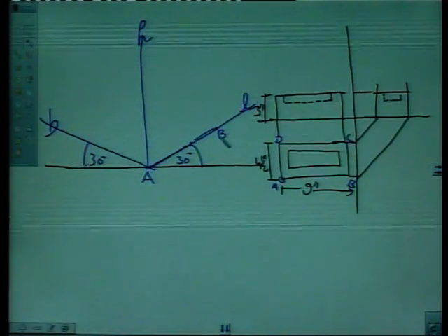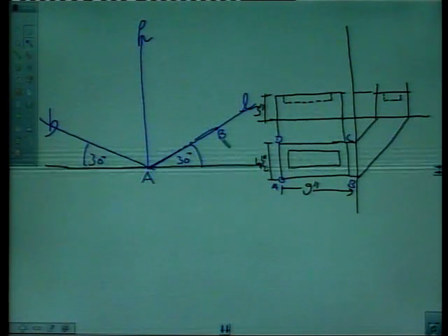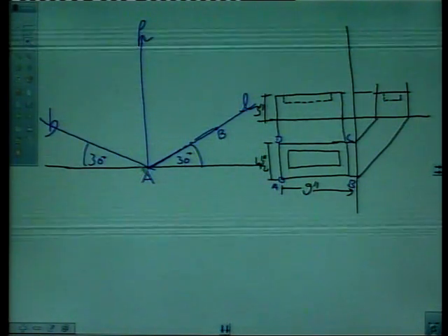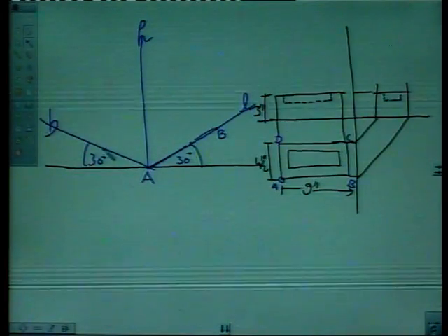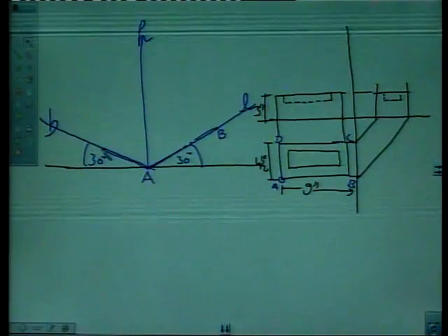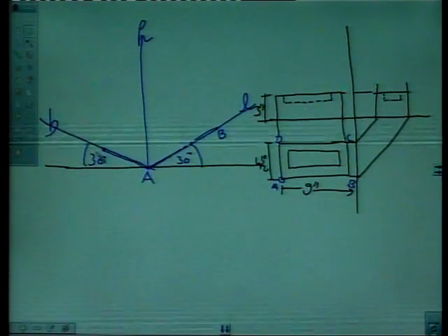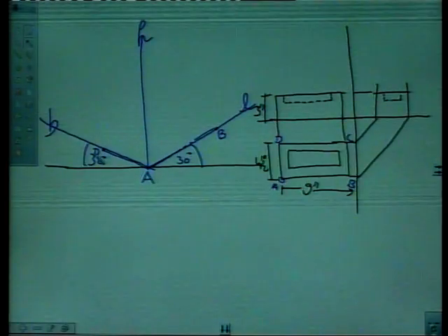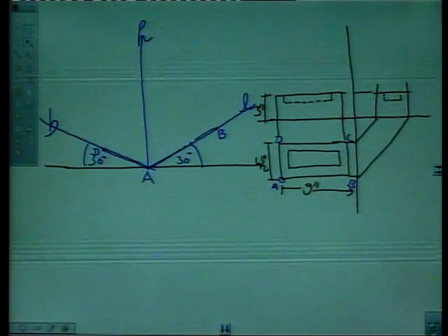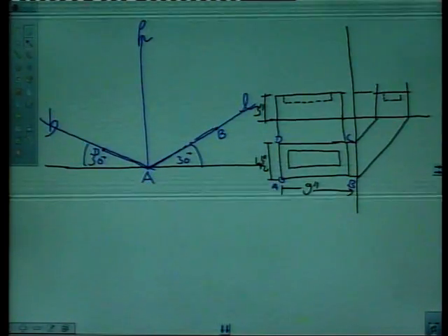Now, mark the point D, which is AD represents width of the brick on breadth line. Say this is 4 inches, right? Now, we have point B and point D here, right? We can mark height of the brick on vertical line, height line, which is 3.